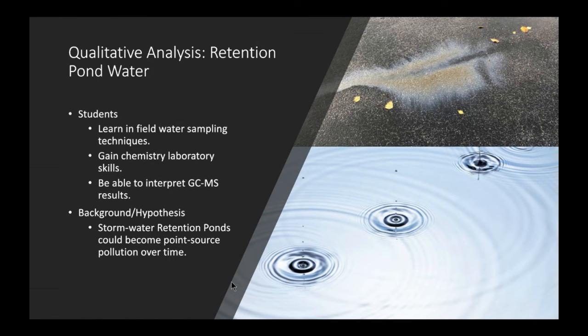Yeah, so I had this idea a while back because in my Geology 111 class in lab, I do a flood hazards lab. And if you weren't aware, these ponds that we have on campus and all around Eastern North Carolina are a very simple way to control flooding. So what they do is they store the storm water temporarily, and they let the water soak into the ground more naturally versus storm drains that pipe it directly to the rivers, and that can cause flash flooding.